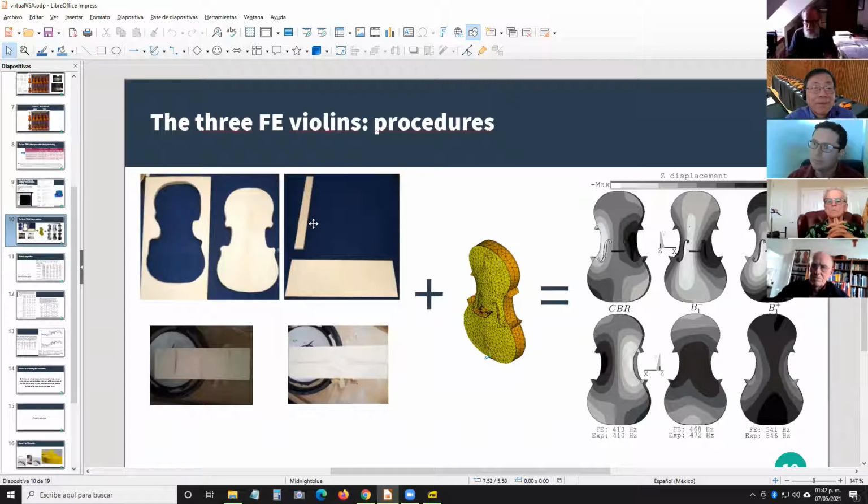You've got a cross-grain stiffness which is the same and follows the arching round, which is what you'd get if you did the Bill Fulton thing of pressing your spruce into shape rather than carving it out of the solid. So you've done something which makes sense to a violin maker, but it's not what they usually do. Don is absolutely right that the properties do vary enormously with grain angle.